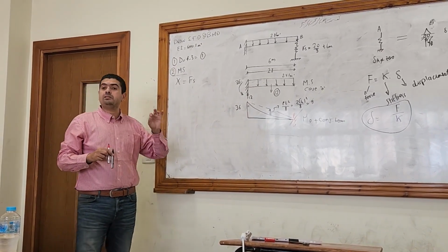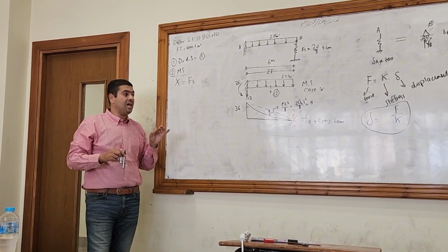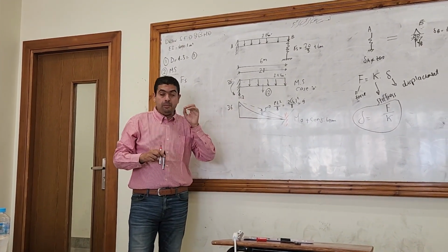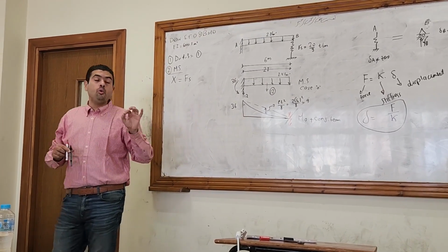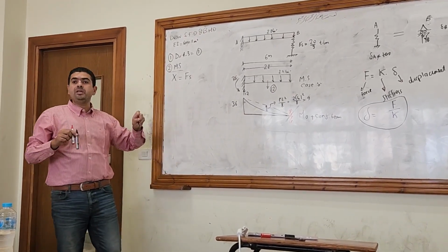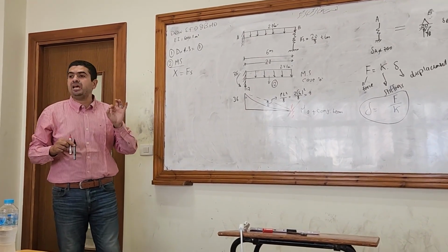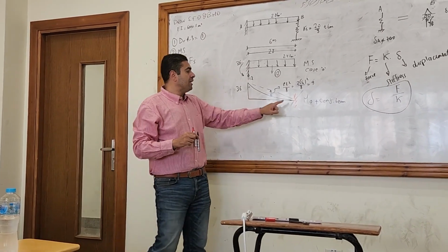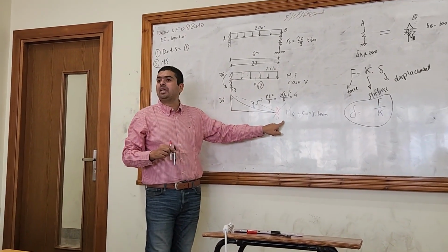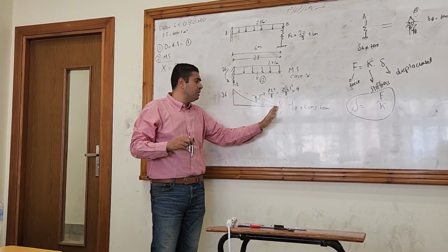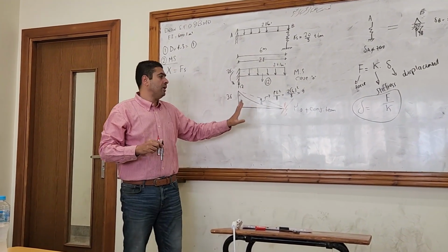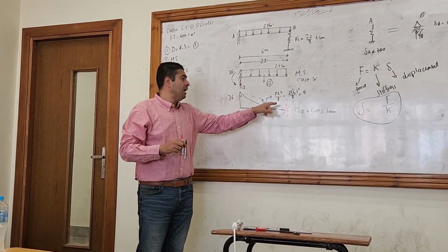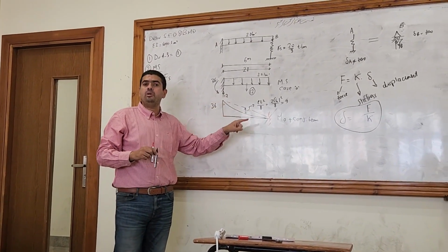What will be the second position where I have to split the bending moment diagram? The position that I remove the redundant from, which is the same as the position where I will calculate a displacement. I removed at B, so I will calculate the displacement at B. B is on the edge, so I have no splitting. It will be, as I told in the beginning, a triangle subtracting a parabola from it.